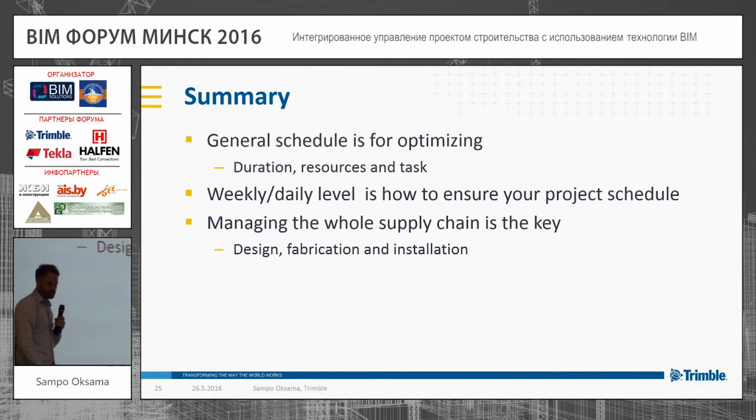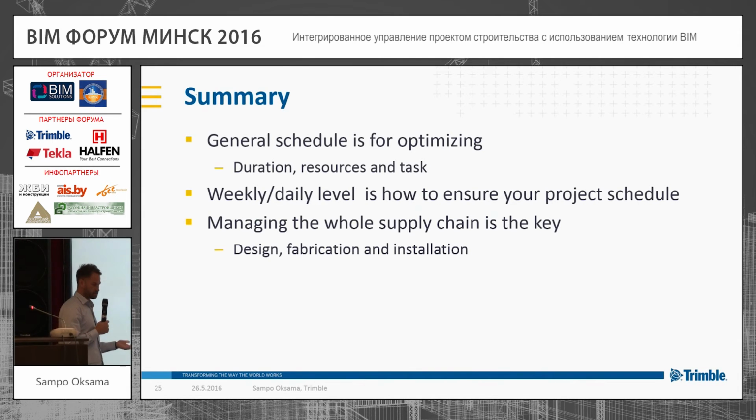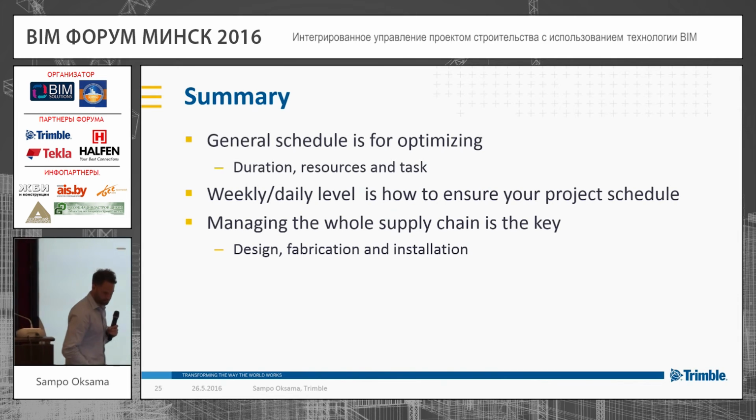So let's make a summary then. The general schedule is for optimizing duration, resources, and tasks. What we have done in Vico Office was that we calculated the quantities, we put in how many resources and workers we need, and then we get the duration and the dependencies between these tasks.